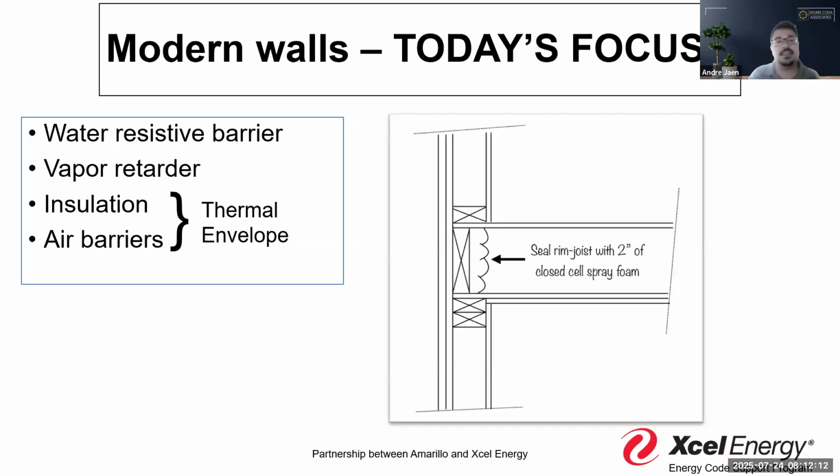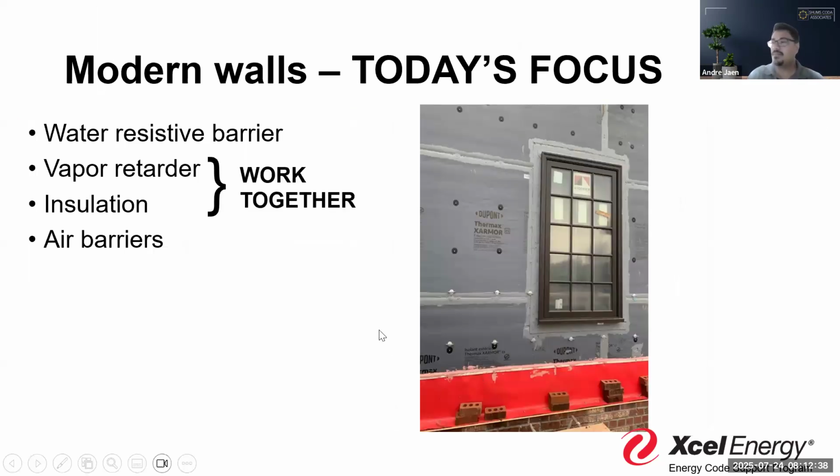So not only are we getting the insulative value out of that spray foam, right? We're taking that R value and saying this is fighting thermal conductance in this space, but we're also getting the air sealing qualities of spray foaming in that rim joist, right? So now we're going to be able to say, okay, it's covered completely with insulation and it's creating that air barrier, which gives us the total thermal envelope continuity at the rim joist. I think it's a really good example of seeing these two work in action.